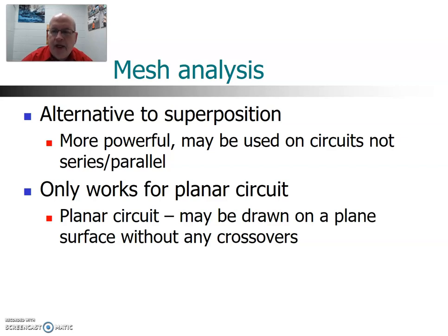Some of you may have already encountered something called superposition. This is an alternative to that, a different way of analyzing circuits, but it's actually more powerful than superposition because it can be used on more circuits, including circuits that are not traditional series parallel circuits. The only limitation on mesh analysis is that the circuit must be planar. And what that means is that you can draw a schematic of the circuit without any crossovers.